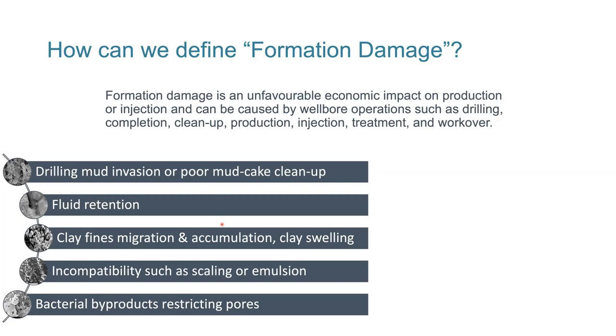And then the last example, there's hundreds of damaging mechanisms, but another one that we see all the time, but not enough people think about, is bacterial, microbiological damage. We think of sour oil or sour gas as an economic problem, a facilities problem, a handling problem. But down in the reservoir, something's happening to generate that sour oil and sour gas. And that's typically bacteria who could be making cell mass, biomass, biopolymer, which is filling up pores potentially. That's a formation damage mechanism.